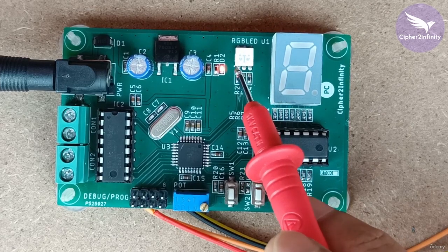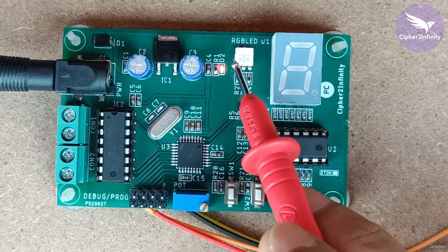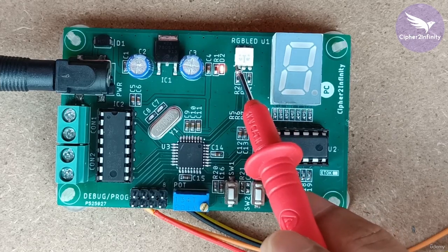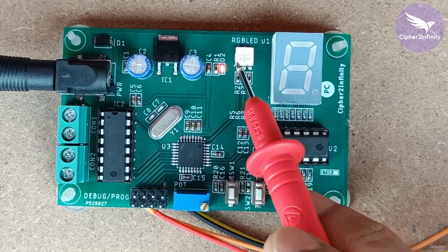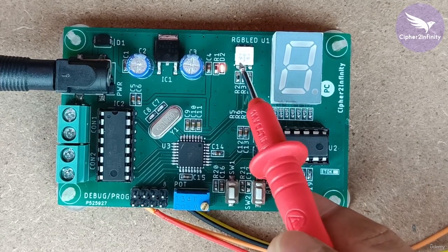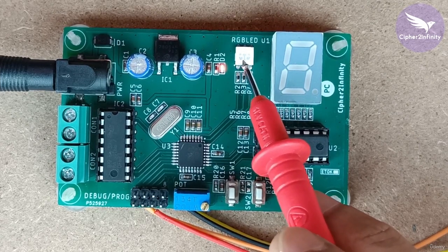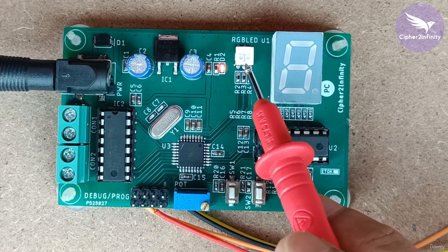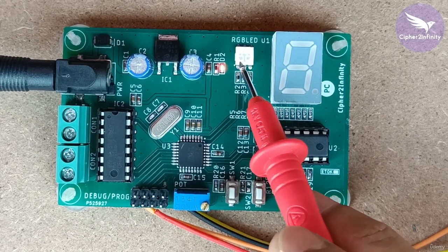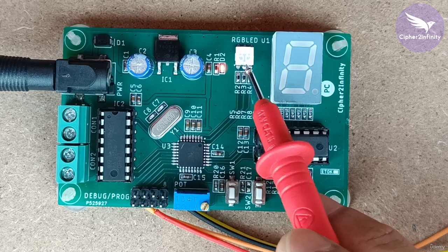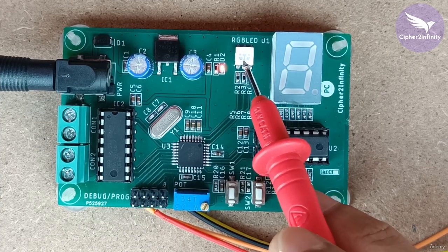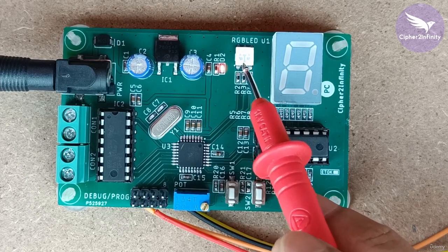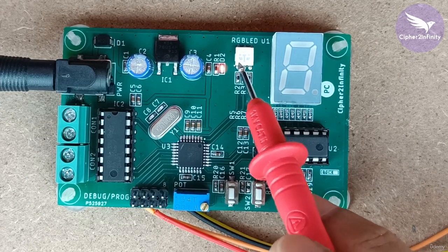And the same thing is true when you are using a hot air gun to solder the RGB LED. You have to make sure that you have set the airflow properly, and you have set the temperature of the hot air gun to the right temperature. Okay. So because of excess heat, you may damage the RGB LED, and you can also crack the glass of the RGB LED. So these are basically 2-3 mistakes that you should always keep in your mind whenever you deal with the RGB LED section.